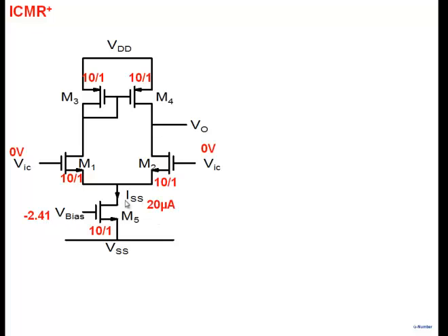Just as an example, the current here is 20 microamperes. Okay, so that's my case when I apply 0 input common mode voltage, and that's my normal bias point. All right, so here, I can also calculate this is 2.21 and 2.21. This is nothing but 3.3, my supply voltage, minus the source-gate voltage drop. All right, so that's the situation at 0 bias here.